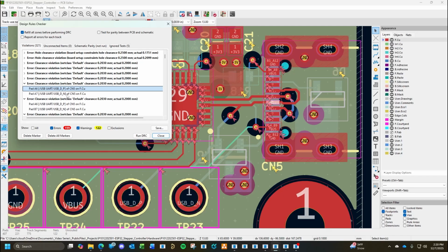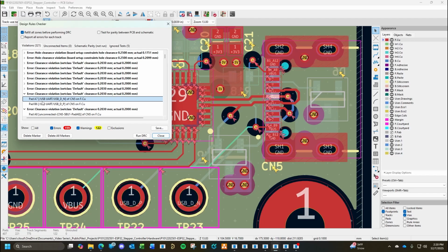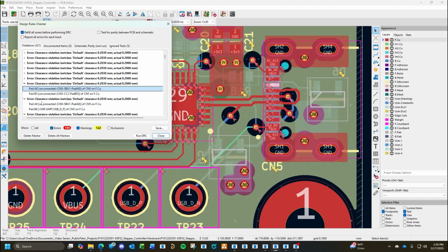But for the sake of what we're trying to accomplish here, okay. Yep, it just doesn't like the clearance. The gap between these pads are just too close together. It'd be nice if KiCad can be told to ignore footprints, to ignore pads inside footprints and stuff, because I built plenty of these boards and the clearance is fine. There's not actually a problem there.